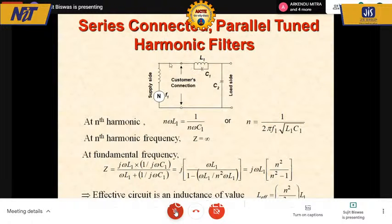It will not be able to flow out because of the large magnitude of the harmonic at the lower frequency, because you see at lower frequency it behaves like an inductance. So inductance means the reactance will be n times larger.